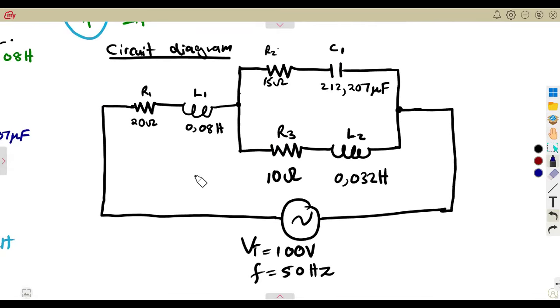So this whole part that we are seeing represents Z1. This whole part here will represent Z2. This whole part will represent Z3. But now we are writing as components, so it's no longer Z1, Z2, because we now have inductors. We have to calculate the reactance to have Z1. Calculate the reactance of this, you combine, you have Z2. You combine this, you have Z3.